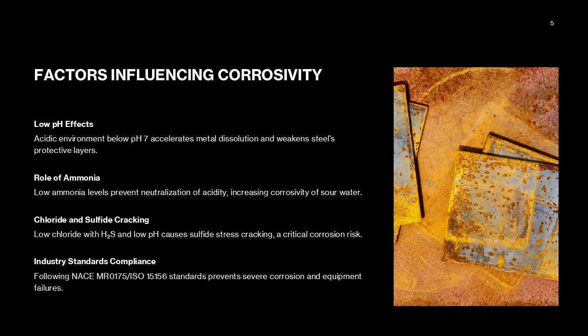Third, low chloride concentrations, less than 50 ppm, combined with H2S and low pH create a unique corrosion scenario where sulfide stress cracking becomes a major concern. These conditions are governed by industry standards such as NACE MR 0175 or ISO 15156, which specify material requirements for sour service environments. Failure to adhere to these guidelines can result in severe metal loss, cracking, and equipment failure, posing significant safety hazards and operational risks. Why acid-sour water is a problem, corrosion and safety risks.